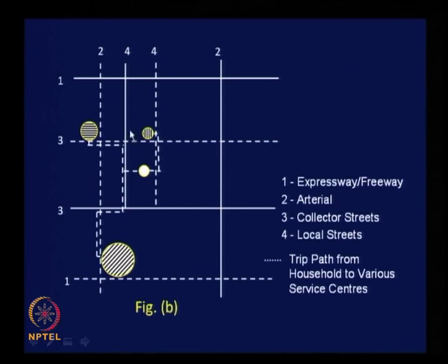So, they just move through the lanes and by lanes in between these roads and reach the class 4 through route, because they have to move over longer distance. So, they have the possibility of taking this through route for some distance and then reach class 3 access route to reach the district center. See, the paths are totally independent of one another. There is no hierarchy maintained in the pathway. Household to community center separate and household to district center another independent path. Look at the path from household to the regional center. They take class 4 through route and then still there is a possibility of moving faster by taking class 3 through route, and then when they come closer to the regional center they get into class 2 access route and reach the regional center.